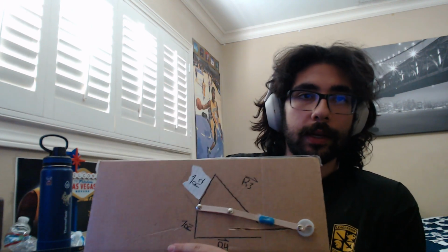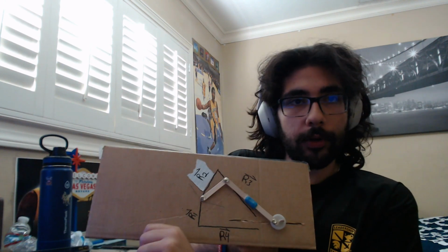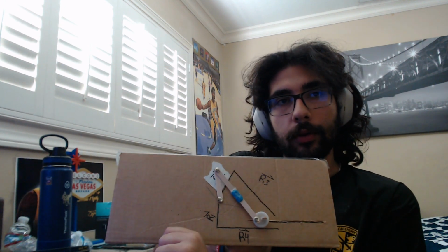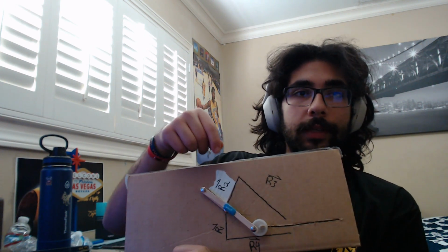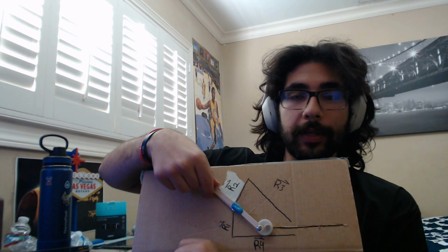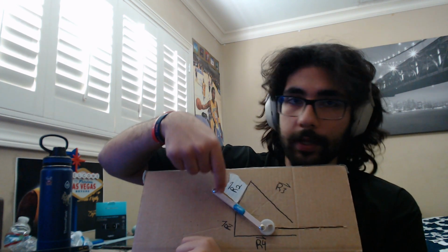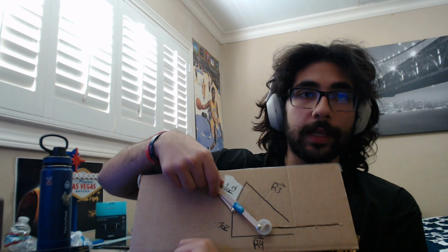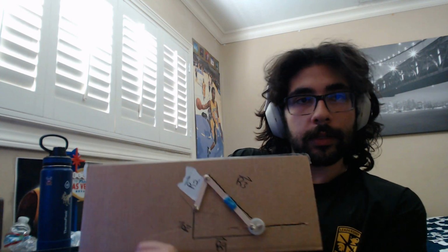So if I go back, there's another dead point when you take it this way, and then you go all the way, the link can no longer move right, because if it moves right it would just rip this pin and send it this way. And also the coupler and the follower are in the same plane of motion again, so it just moves left and right like this. Very cool.